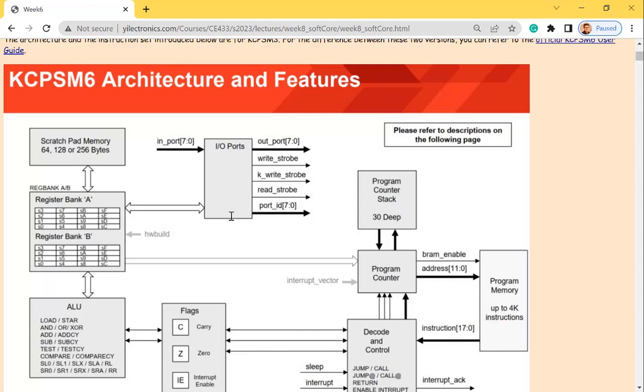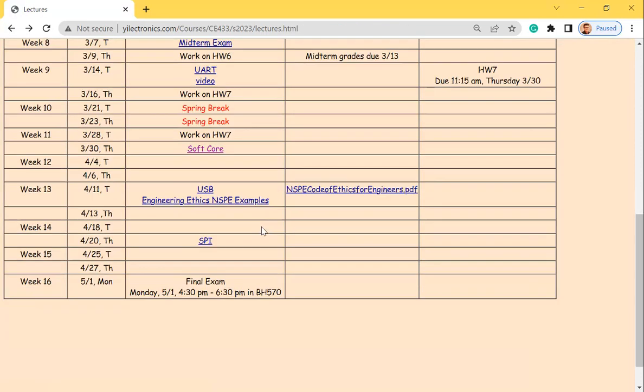A lot of things. And if you put an I2C core in it, we don't cover I2C here, but we do cover SPI. Have you used SPI so far? But you used I2C for the oximeter, right? Yeah, it's just Wire.h. But SPI, I think we will have the chance to do it with the very last project in microcontrollers, because usually the IC cards have an SPI interface. It's easier than I2C. It has 4 pins on it.